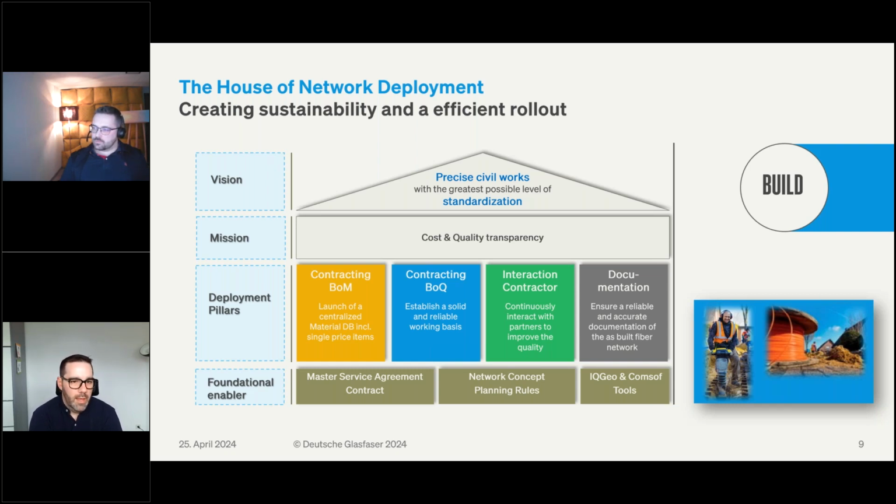It describes not only, for example, a 96 fiber cable, which Jakob is planning. We also have the cost, for the calculation of how much it costs to have the network rolled out. We will also have things like data sheets and installation manuals for our contractors directly linked in this tool. And we have the attenuation values, which show you the whole attenuation between your active POP, for example, and the customer, to see whether the technology you want to provide on this network fits.